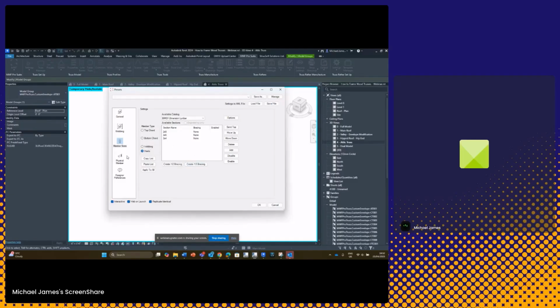Okay, we've got some physical options as well. So you've got top track insertion width. You've got options to add extra insertion thickness if you need it. You've got chord pitch break. So when you've got the top of the truss, you can have the two members overlap, or you can have it open. So I'll say lapped. And then you've got chord end cut, which can be cut from the inside or from the outside. You've got the option to define these things here.